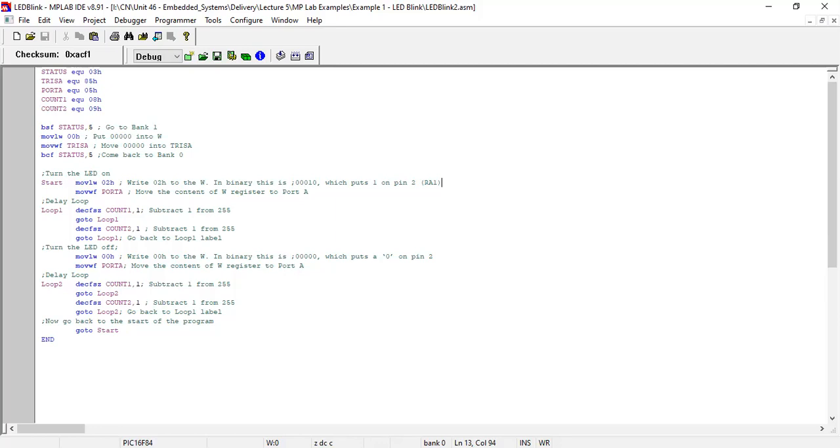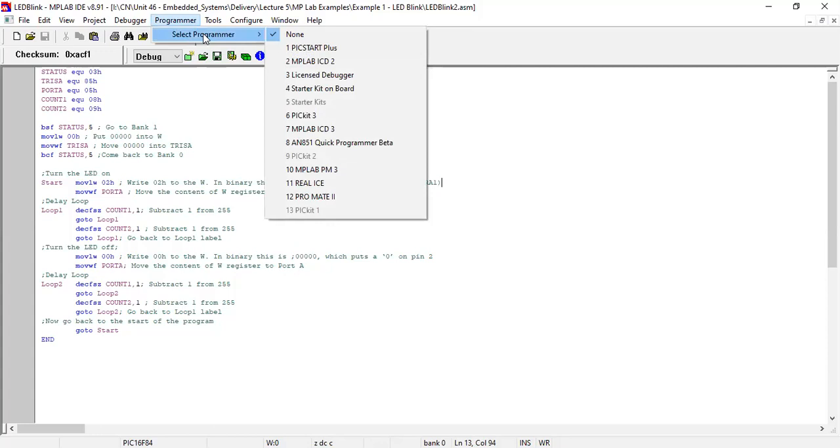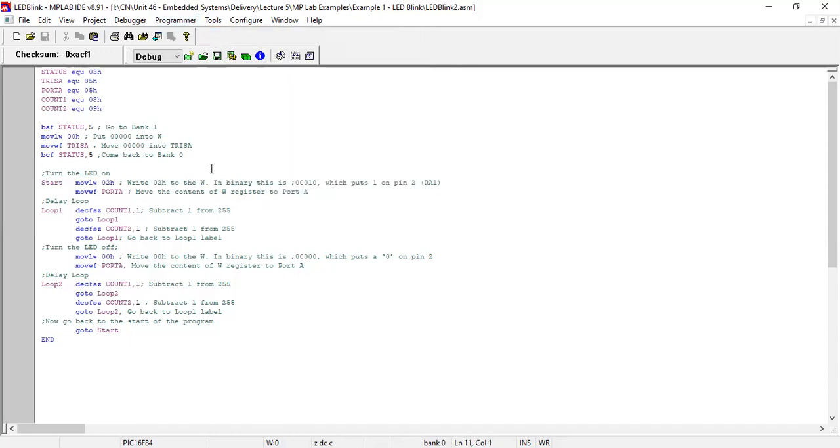After putting that file into Proteus for our PIC, we can run and simulate. The same thing will happen when we are doing it in the actual world. In order to do that, we need PICkit 2 or PICkit 3. Using this program, you can program it as necessary. And here it doesn't have PICkit 2 now. So like that, you can try.